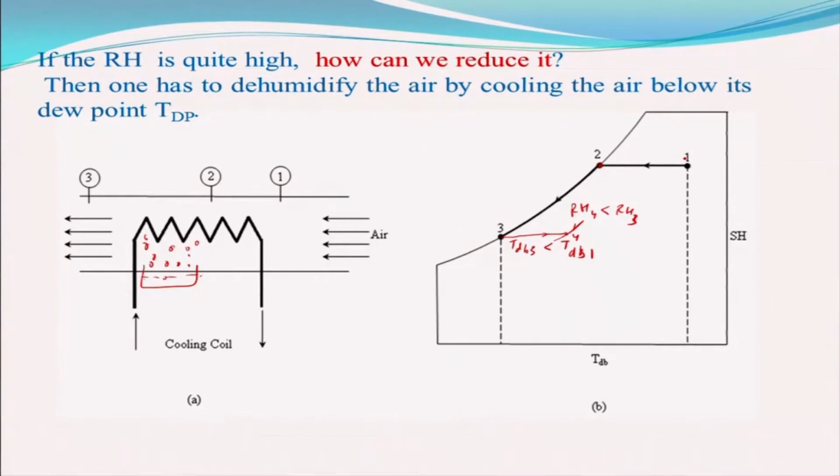But there is another way of solving the problem: you mix some other air which has a different relative humidity and specific humidity, and then you can get this. This mixing of moist air at different temperatures and conditions is used routinely in air conditioning applications. So we will be looking at the adiabatic mixing of air streams.